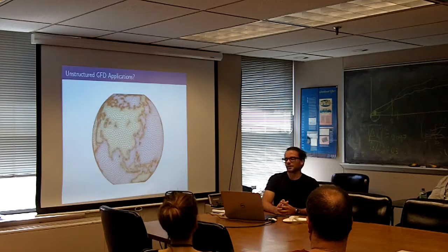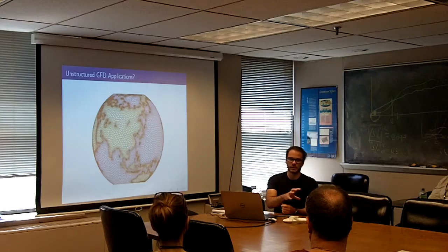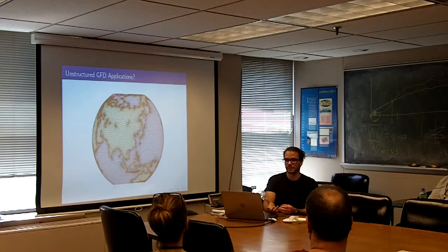Why? Where will it break down? With a uniform mesh, you essentially only need to compute all of the interpolation coefficients that you use when evaluating the fluxes just for one element, because then you can just map that element to any other element in the mesh. With an unstructured mesh, every element is special, essentially. So every element needs to be treated as a special case. So you need to compute and then store all of the interpolation coefficients for every element in the mesh.